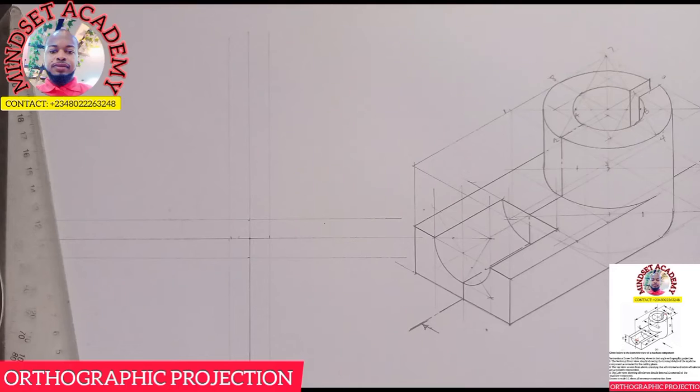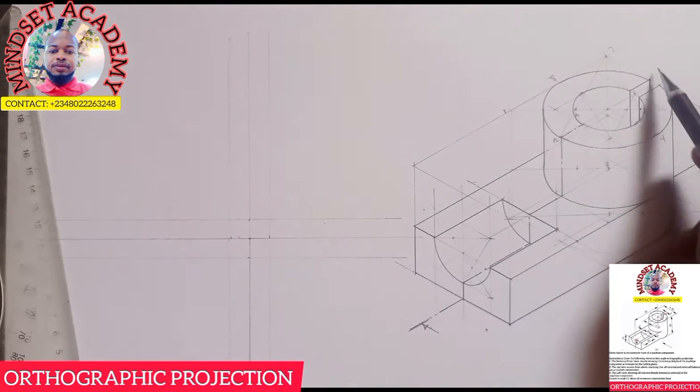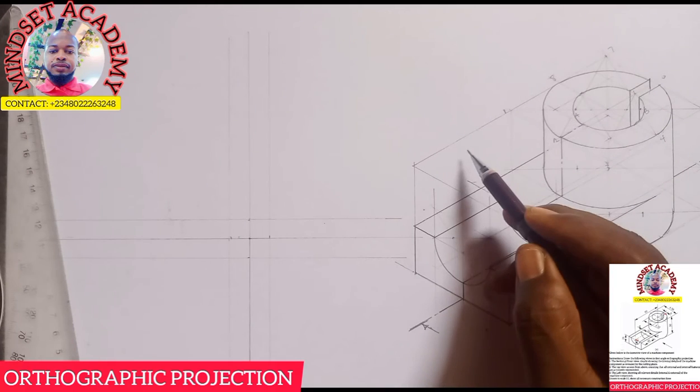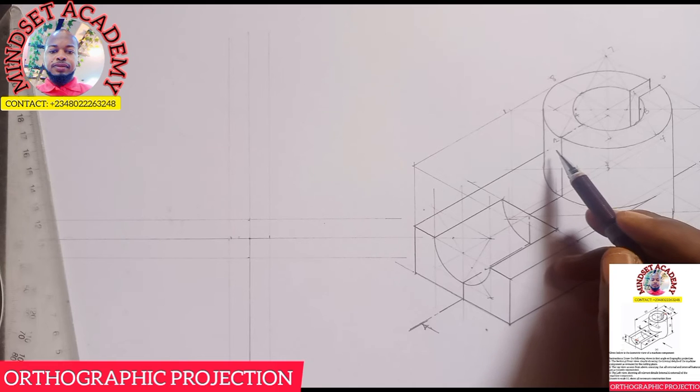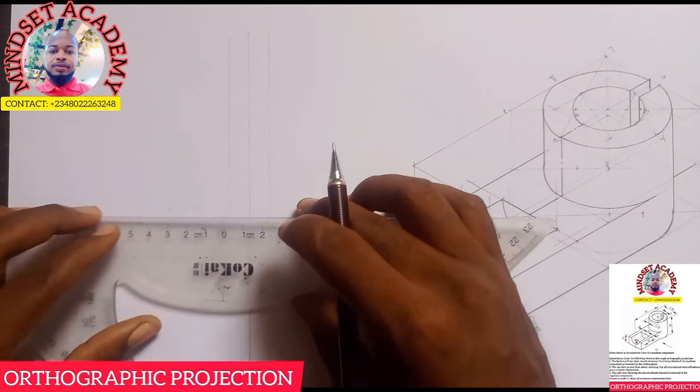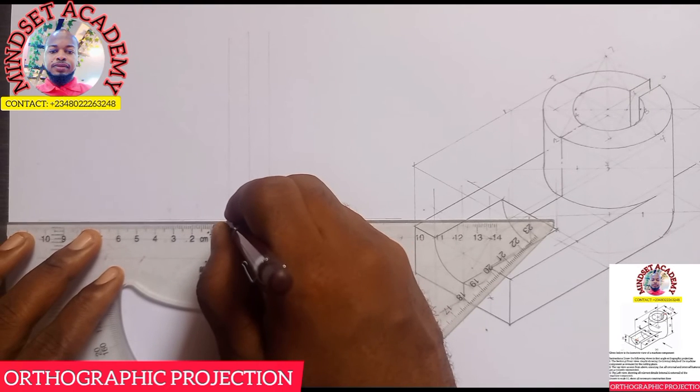So before sectioning, let's draw what we see looking at it from this side. Now you see the entire length here. Like I told you earlier, from this end to this end here is 118. How do you get that? If you look at your diagram closely, the diameter of this circle is 56, making the radius 28. And from this end to this center here is 90. So 28 plus 90 is 118. Is that okay now? So 118, that's what I'm going to measure from this end here, from 0 to 118.